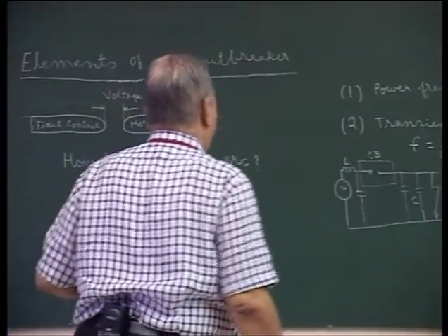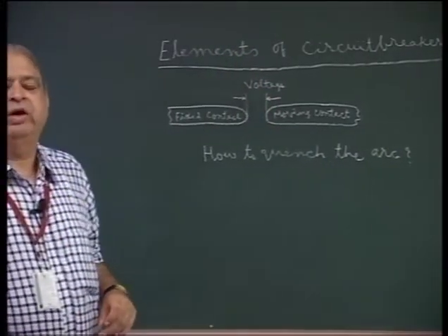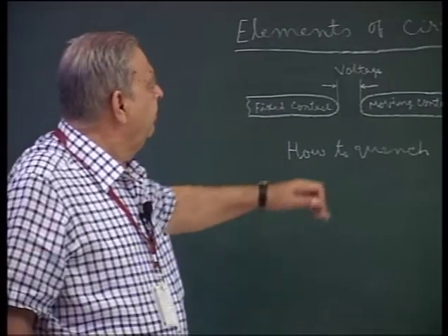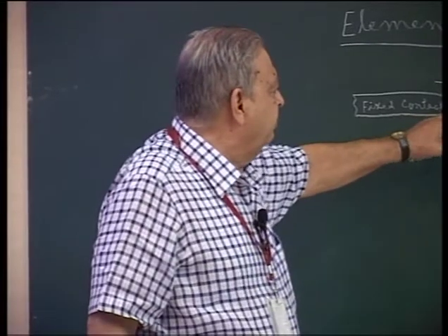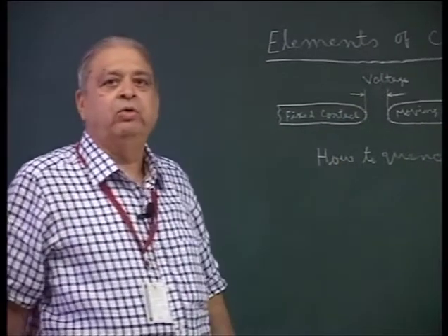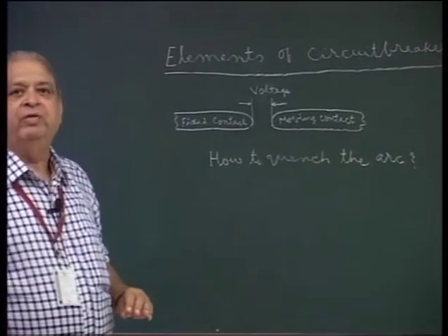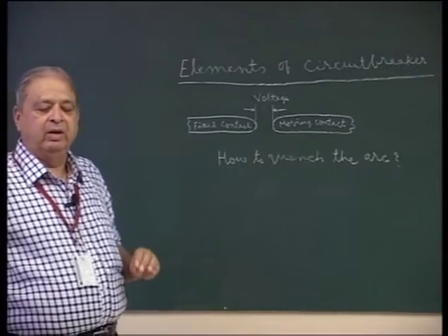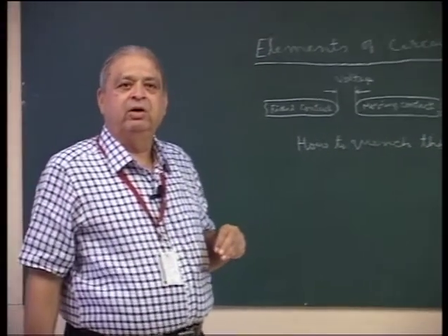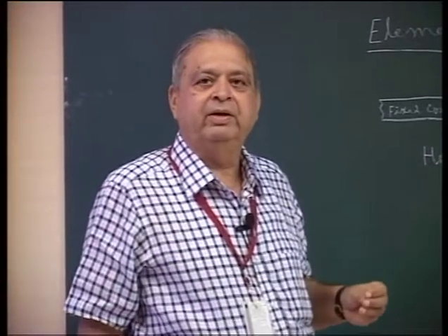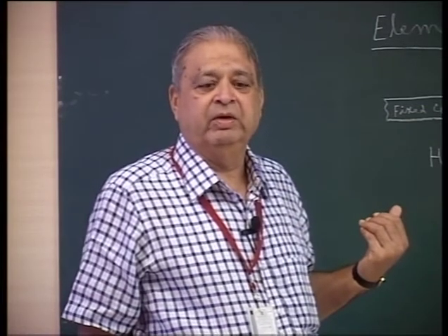The contacts are open, and in all the circuit breakers, we make efforts to cool the arc path. This path we will try to cool by forcing more media in between the contacts. Also, we will generate mechanical forces to mechanically move away the ions due to previous discharge.